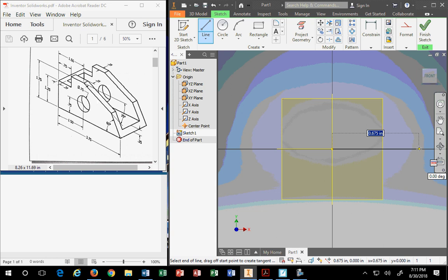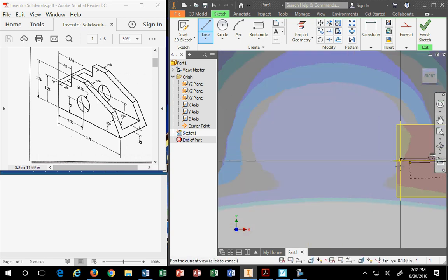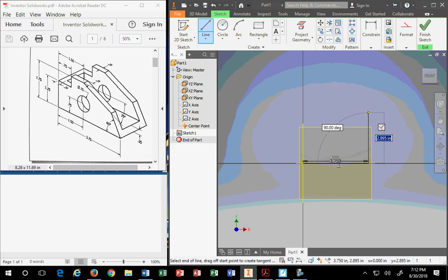You'll notice when you move it over, you see that box that has that number in it? 0.625. It even tells you the units, IN, for inches. Well, what's the length of this thing? 3.75 based on the drawing, correct? So we're going to type that in, 3.75, and we're going to hit enter. And poof, not only did it drop in the physical line, guess what it also dropped in? My dimension. So talk about lazy. Get it?